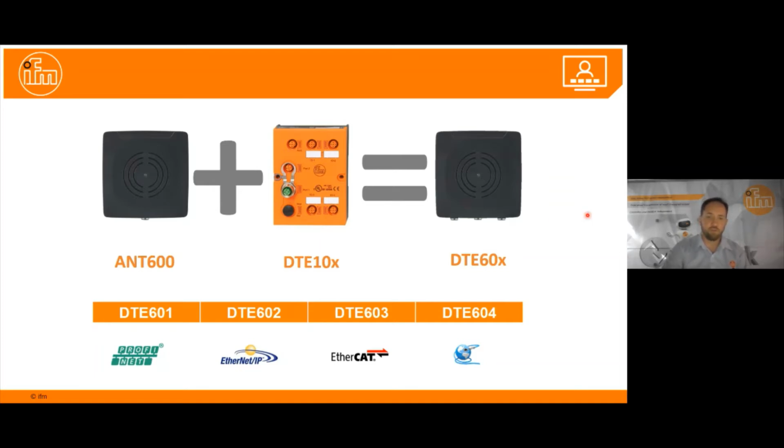Where you'd use the DTE6 is where you have multiple reading and writing applications that spread out further than 20 meters. Or there's possibly an economy where you've got 2 readers about 20 meters from each other, and it's a maximum of 2. The cabling, etc., may work out a bit more reasonable if you use the DTE6 versus the DTE1 series.